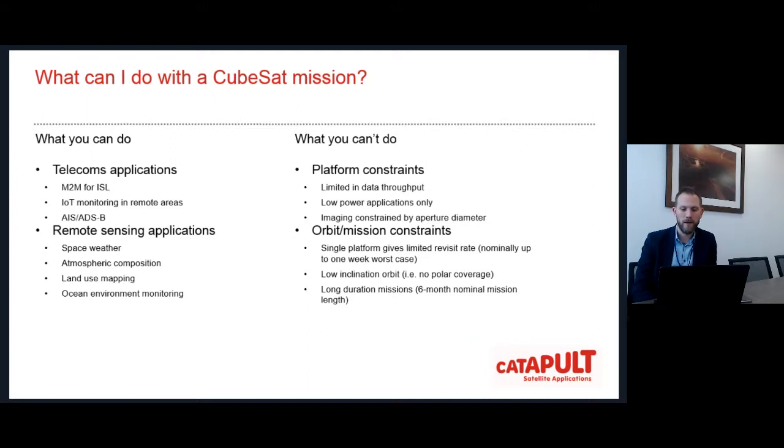And long duration missions are also challenging due to the low altitude at which the ISS deploys CubeSats. 6 months is our nominal mission duration. 12 months is probably about the realistic lifetime on average you would expect for the orbital lifetime before the spacecraft re-enters and burns up. So that's the kind of order of magnitude that we're looking at.